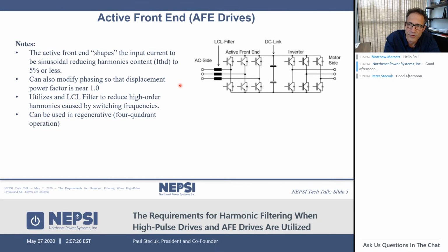One of the things that's interesting about the active front end drive is they utilize an LCL filter on the front end because of the switching frequency associated with the front end of these drives. That LCL filter consists of capacitance and reactance. And when doing harmonic studies, it's important to actually model this front end of the active front end drive, because it is a small amount of capacitance and it will create a resonance in your system.